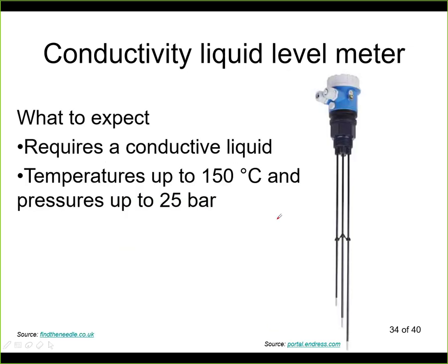What can you expect? Now this needs obviously a conductive liquid. So if the conductivity is above some minimal level, it will work. It will work for temperatures of approximately 150 centigrades, pressures about 25 bar. Again, those numbers are from manufacturer data sheet, so I've selected one manufacturer and those are the numbers. Others may be providing different temperatures and pressures. That's clear. And here we can see an example.